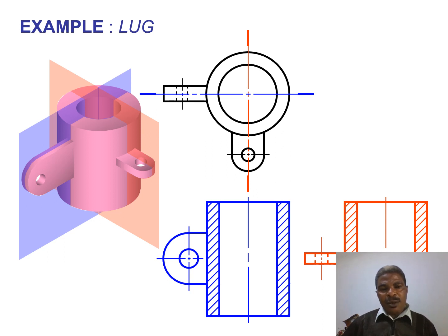This is rather vertical, and this one could say is lying in horizontal. The flatness is on horizontal, this one is in vertical. So to indicate it very clearly, 2 cutting planes are laid for the same object, because these parts differ. So if you want to elaborate it more, you need to have two cutting planes of a single object.